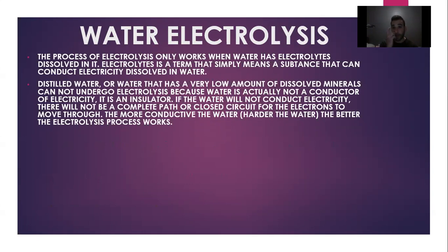The issue is the harder the water, the more minerals, the more scaling is going to happen to the machine, to the device. So if someone's living on a well, or they live in a city where the water's harder, they'd have to make sure that they're doing their e-cleans more frequently to make sure that they're descaling the machine.